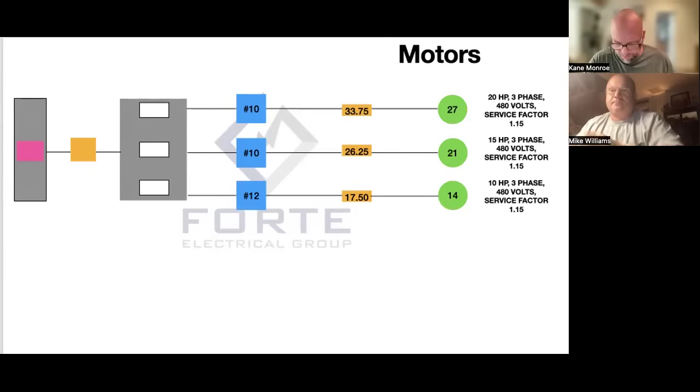Let's go to step number 5. So is the 1.75, 175%, the number we're looking for on these? No. On step number 4, you're looking for a breaker size, the size that comes out of 240.6. So we're looking for, let's see, the FLC of this motor is 27.